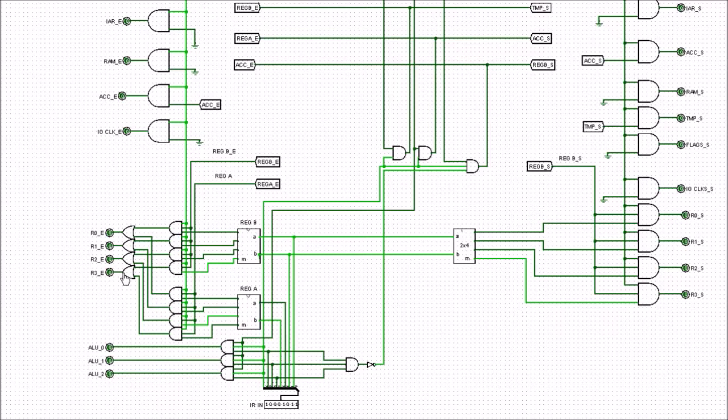Okay. Now it can't actually choose register 3. There are 2 things that have to happen. One, the clock has to go high, which it is at the moment. But there's another thing that has to happen before it's able to choose that register. You can see here there's a connection, if we take it out here, and it goes up to this thing called Reg B. That is just another part of the circuit. So somewhere else within this control circuit is determining whether we actually allow the control unit to choose this register 3.